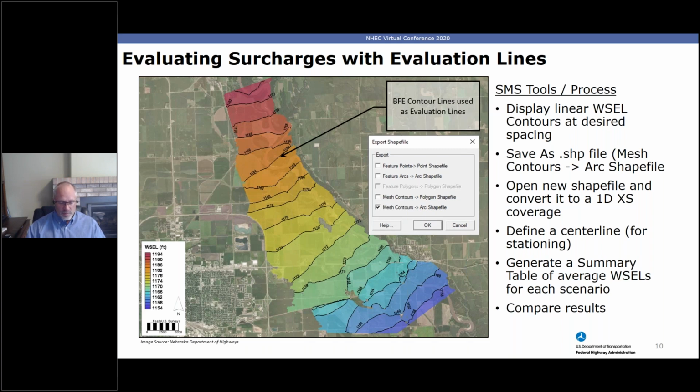So I guess, Wes, the best answer to that question is coordinate directly with your floodplain administrator, because that's the most important point of contact. Even when this official guidance does come out through FEMA, it's still going to be up to the guidance or direction of the local floodplain administrator. As Casey will show in a few minutes, he's got a project in Washington State where they used 2D modeling for a no-rise analysis, even though the official guidelines aren't out yet. And I know folks in Colorado have been doing the same for evaluating floodway surcharge.